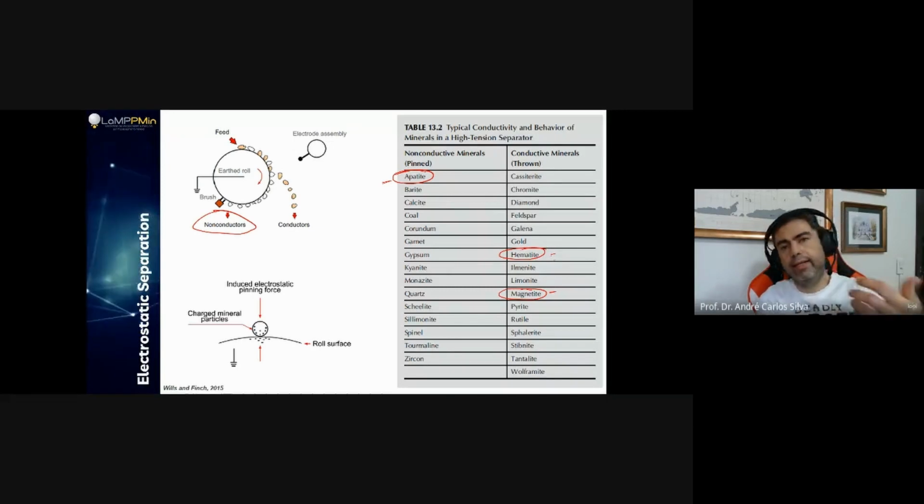Okay, and then we have the problem of the particle size. If I try to use this equipment with coarser particles, then I have mixed particles, and then I don't have the response that I want. If I try to grind down the material and mill it, then I have particles too fine that I can't use the equipment anymore. So that's the situation that I have to tackle.